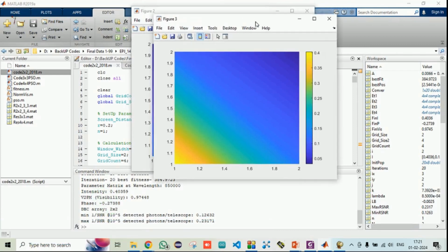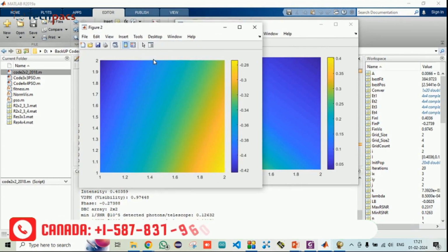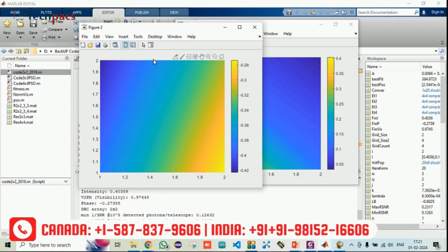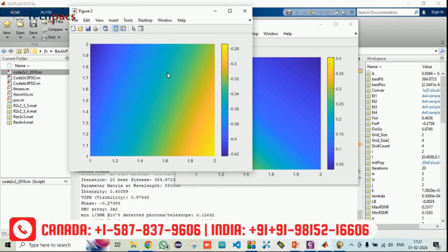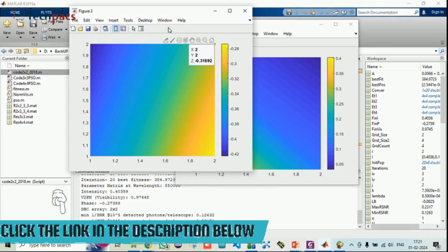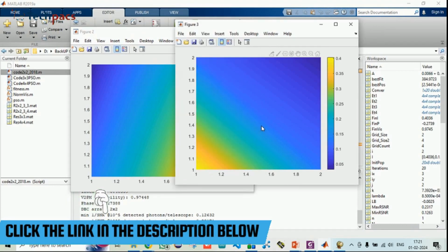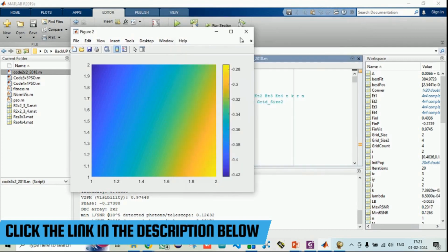So this tells us which waveguides out of 2 cross 2, meaning a total of 4 waveguides, we need to select in order to combine the laser so that the maximum visibility and highest intensity can be achieved, and at which phase the signal will be there. So these are the light waves that we have achieved from the simulation. So this is for 2 by 2.